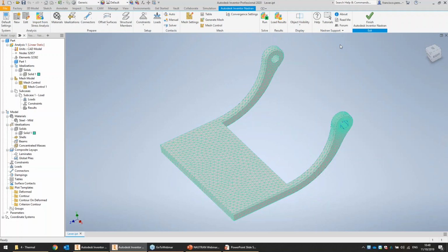One of the ones I will impart to you today, if you're looking to ensure that your results have fidelity, there's a good rule called the rule of three, which involves using 3 different mesh refinements when doing a calculation. So you might put a load on the lever, calculate your stress, and then you'll refine the mesh a bit, and then recalculate, and then refine it once more and recalculate. And if you see that the results are asymptotically approaching a static value, then you can say, okay, yes, this mesh is converging, and the results can be trusted. Not all the time, but as a good rule of thumb.